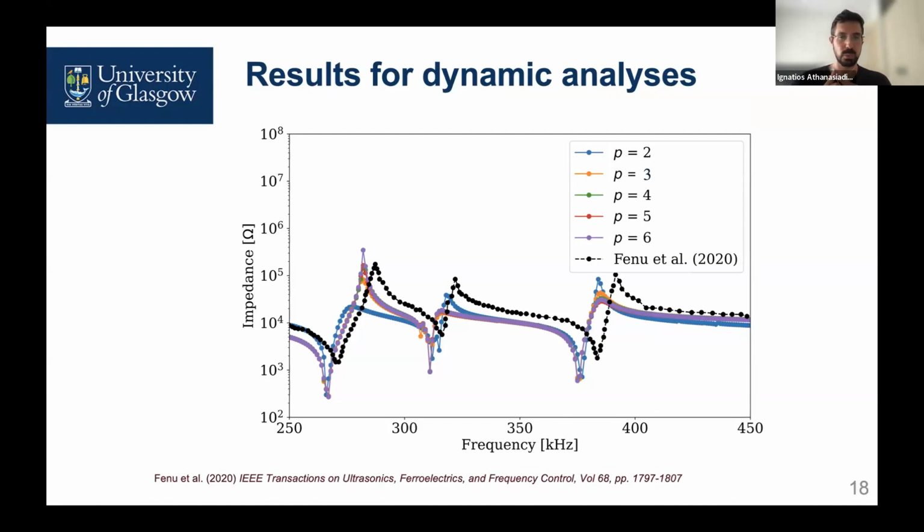And on top of this, we realize that we don't really understand what damping actually does, especially for higher orders, because here you can see that with black color, these are the results from this paper, and everything else are results from MOFEM for various orders of approximation. So we realize that for different orders of approximation, depending on the base that we use, we have a different behavior of the damping parameters.